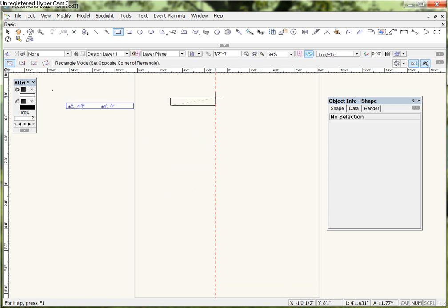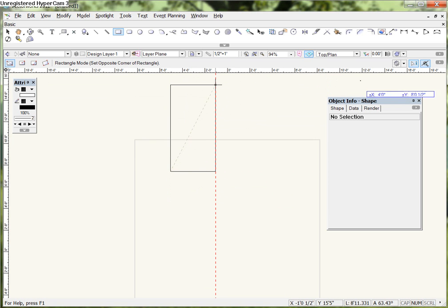And see what that's done is it's taken our X direction, that's this direction across the screen, remember Y is up and down, and it's put this little red lock in here, and it's actually locked this one dimension into 4 feet. So I still am flexible about what the Y is doing until I give it some sort of number, but my 4-foot is locked into place.